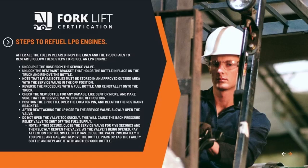Unlock the restraint bracket that holds the bottle in place on the truck and remove the bottle. Note that LP gas bottles must be stored in an approved outside area with the service valve in the off position. Reverse the procedure with a full bottle and reinstall it onto the truck. Check the new bottle for any damage, like dents or nicks, and make sure that the service valve is in the off position. Position the LP bottle over the locator pin and relatch the restraint brackets.